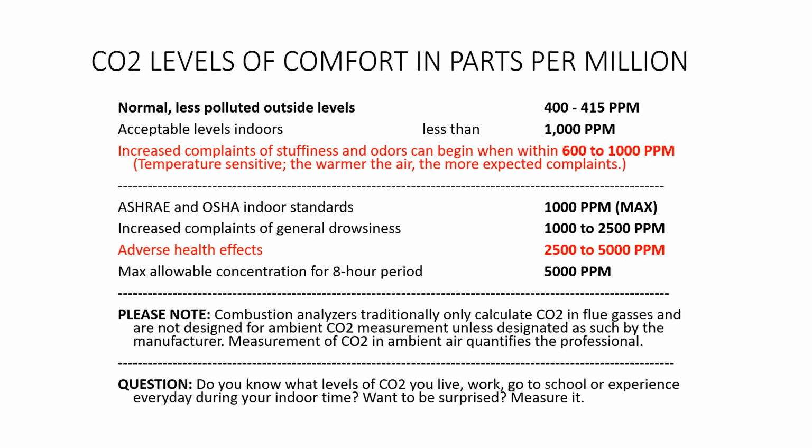600 isn't that far off from fresh air. That's only a couple hundred parts per million. So it's got to be pretty warm inside a home for complaints to begin that low. But when we get over 1,000 parts per million, that's where you get increased complaints of general drowsiness, and that goes up to 1,000 to 2,500 parts per million.